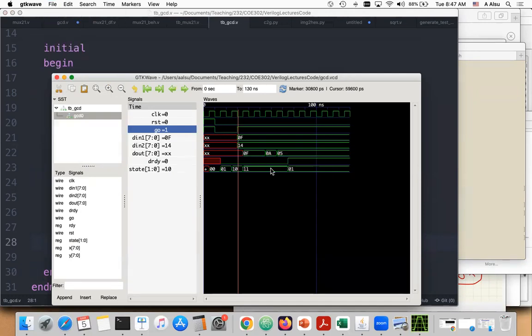You see, now it's working. This is what I suspected. You should give it more than one clock cycle to change. So basically, you need go to be detected as a 0 first at the positive edge, and then as a 1 at the next edge.